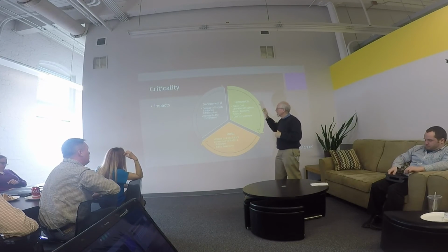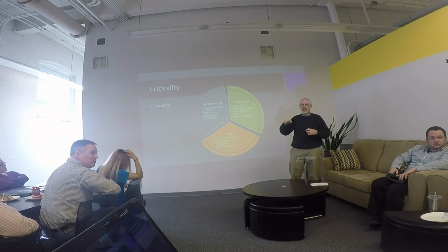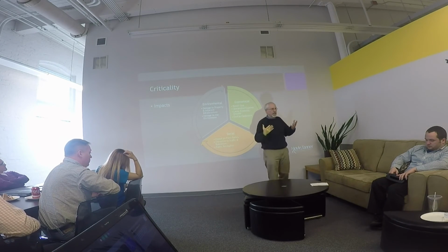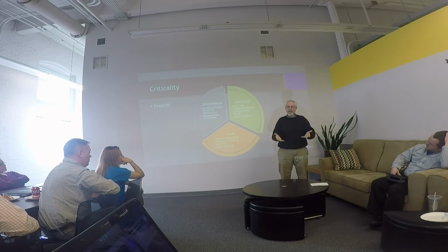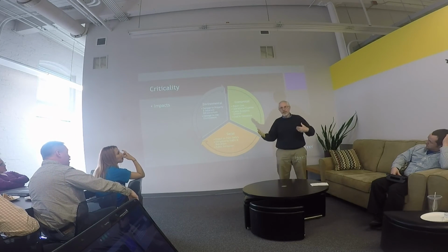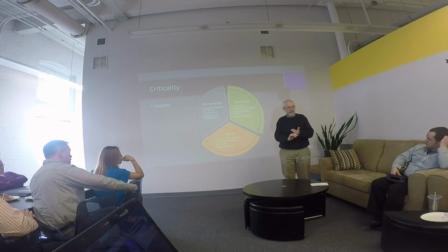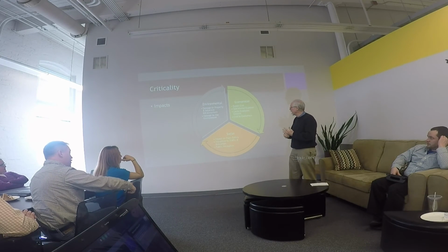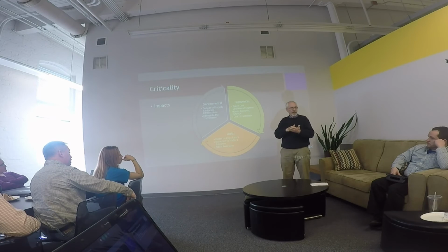Okay. Criticality is, if an asset fails, what is the impact? Is it environmental? If a sewer along the river fails and it dumps right into the river, and right downstream a mile is a water plant sucking in the water, it's a high risk. It's an environmental risk. That is also social, because they'll be in the paper and they'll have your organization pretty well up in front. So you look to see if something fails, is there an environmental impact?